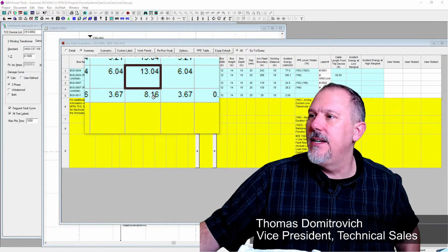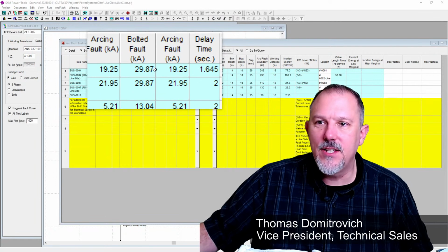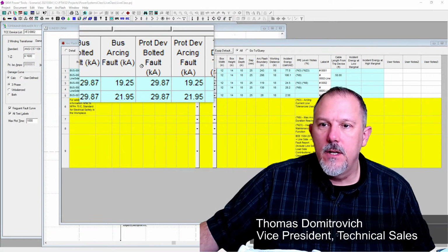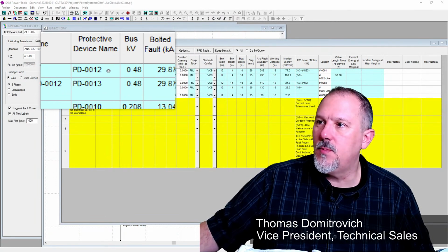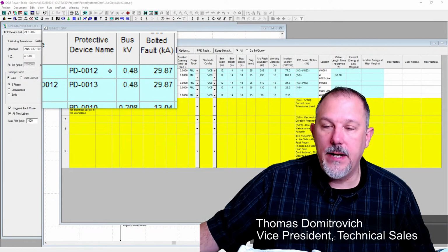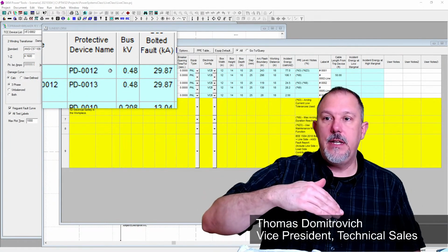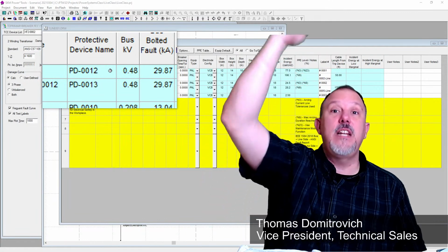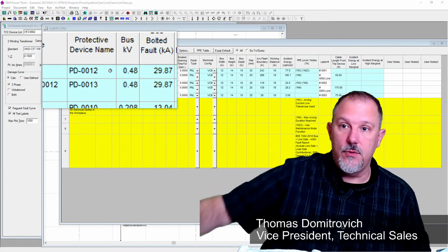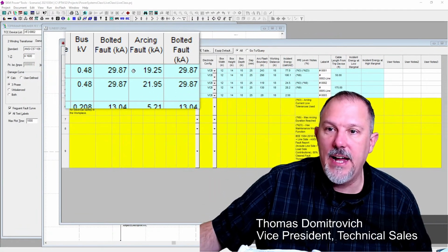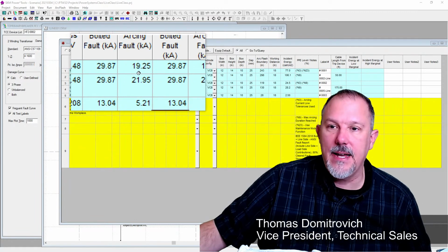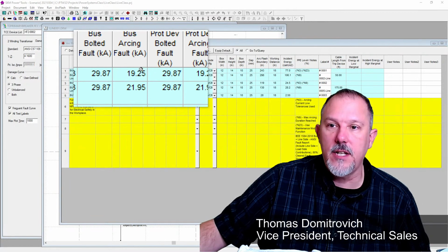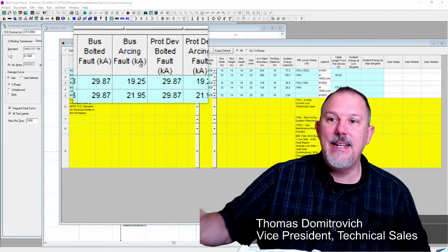Mohammed. Thank you, sir. Okay, so here it is. All right, so this was PD12, right? PD12 is the downstream device. PD13 is the upstream device, the fuse. At PD12, I have a bolted fault current of 29,870. My arcing current is 19,250.